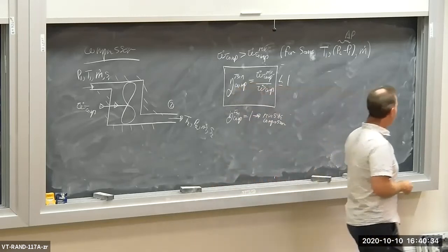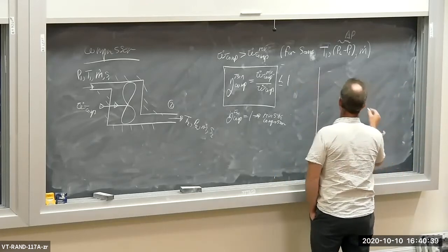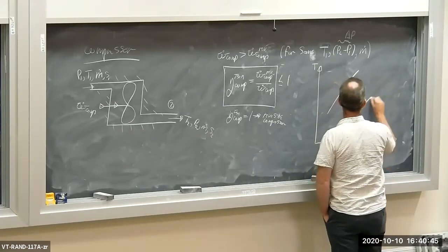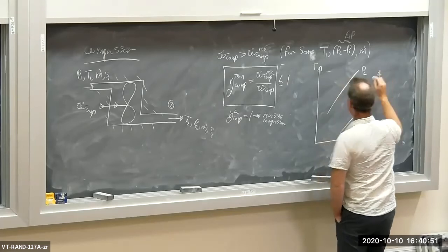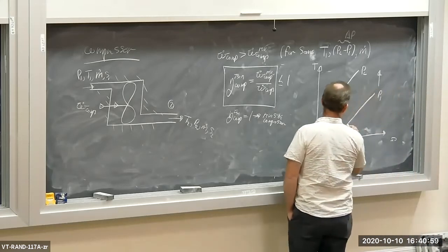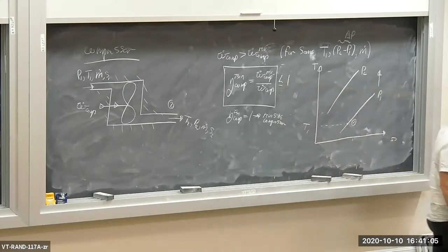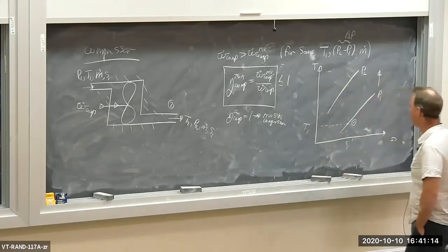Okay? Let's draw the TS diagrams for the reversible and the irreversible or actual compressor. Same two pressure limits. So we're going from P1 to P2. So pressure is going up as we compress. That's what a compressor does. Pressurizes the flow. So state 1 is right here. Both the reversible and the real compressor start off at the same temperature T1 and the same pressure P1. And of course, we have an S1 right here.